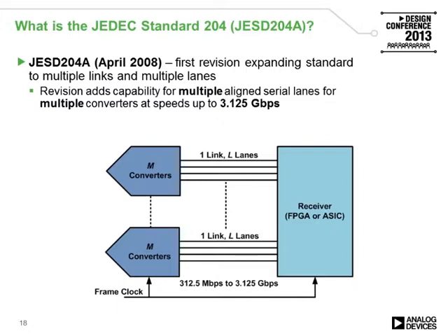Although both the original JESD204 standard and the revised JESD204A standard were higher performance than legacy devices, they were still lacking a key element. This missing element was deterministic latency in the serialized data on the link. When dealing with a converter, it's important to know the timing relationship between the sampled signal and its digital representation.